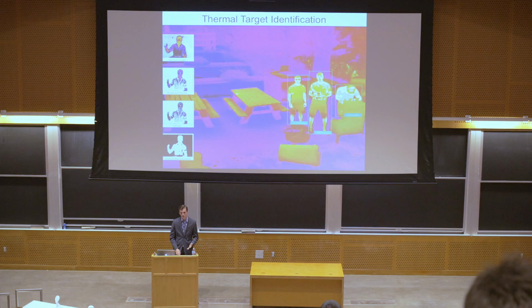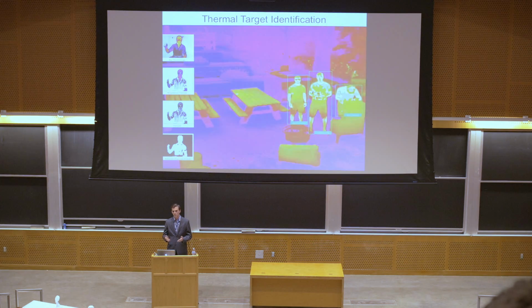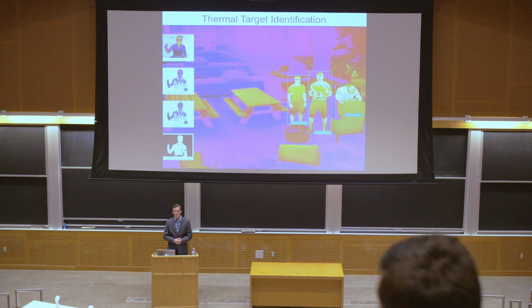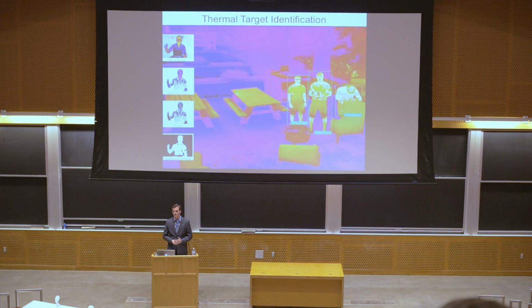The idea here is essentially that if two or more roughly elliptical blobs that are large are in a certain area of the frame, we have a high probability after post-processing of that being a survivor, and so we flag it as one. Upon successful identification, the UAS takes a picture of that and sends it back to the first responder so that the first responder can visibly inspect this, easily tell whether it's a false positive or not, and we can get a response effort out and into the field as quickly as possible.